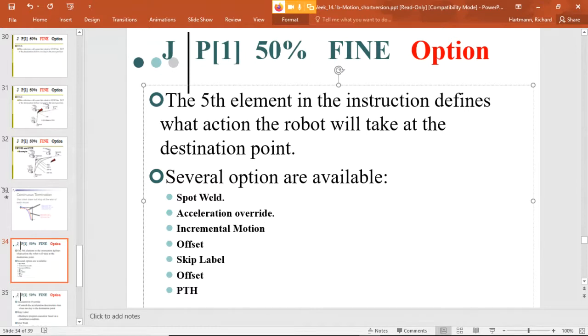Because with a big heavy load, if you're jerking around a lot, that puts a lot of extra stress on the joints of the robot. So you may want to go as fast as you can, but not speed up too fast, because if I speed up at an easier rate, there'll be less wear and tear on the robot, and also less chance that it might slip out of the gripper of the robot.